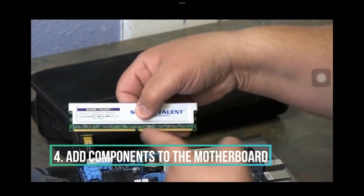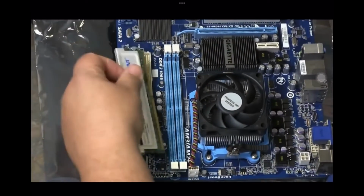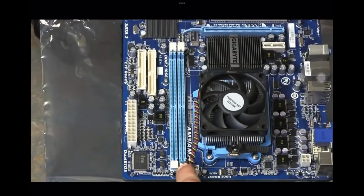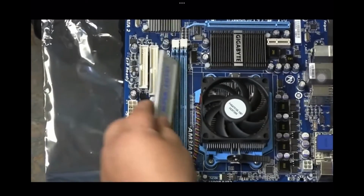Step 4 is add components to the motherboard. This is usually easiest to do before you install the motherboard, as the case can limit your ability to wire components. Attach your RAM to the motherboard by finding the RAM slot and inserting the RAM appropriately. They should only fit one way.